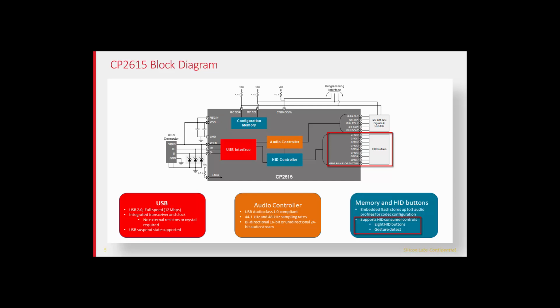And this is something that we give off the shelf as a turnkey solution of the 2615. But if a customer is trying to roll their own with their own embedded MCU, they're going to have to learn all the intricacies of the HID class and figure out how to properly report all of these button events. So it's something that absolutely speeds time to market for our customers.